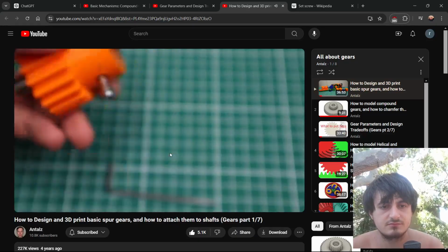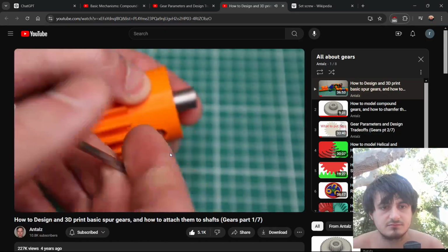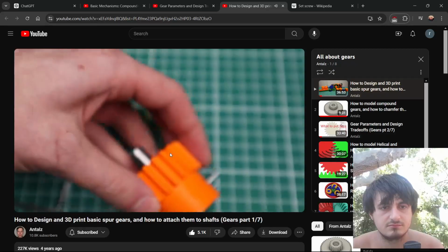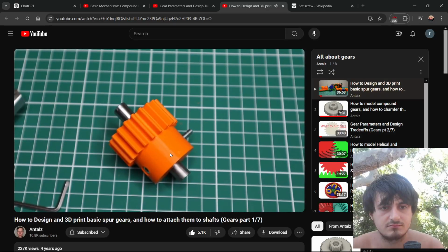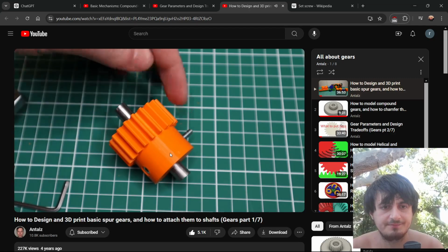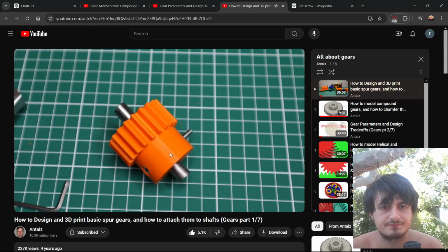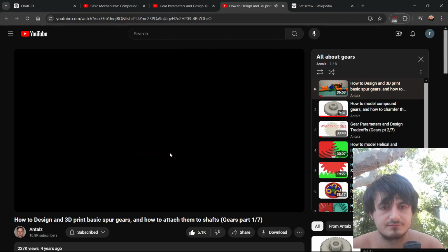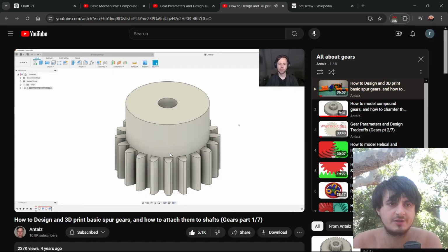And then once it engages with the nut on the other side, you can use an Allen wrench to tighten the screw into the nut. And then we have our finished result. The benefit of using this technique is that you can transfer an enormous amount of torque through this system. There is no way for this mechanism to come loose due to a simple deformation. For this mechanism to fail, something has to break. Either the shaft, or the screw, or the gear itself has to break into pieces, or otherwise this mechanism will stay intact.